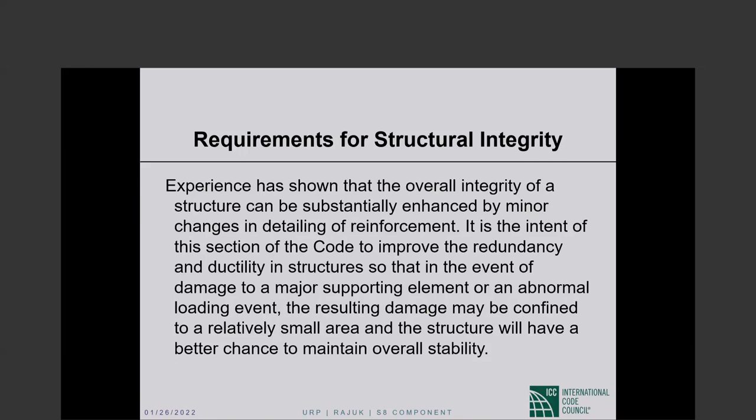Dowel is something that, think of it, so we do the footings first and then the columns go on the footings. Bars stick out of the footing and those bars are called the dowels, which are then lapped with the column bars. There are no hooks involved in this picture. These are straight dowels that are lapped with the column bars, and that's how construction starts.